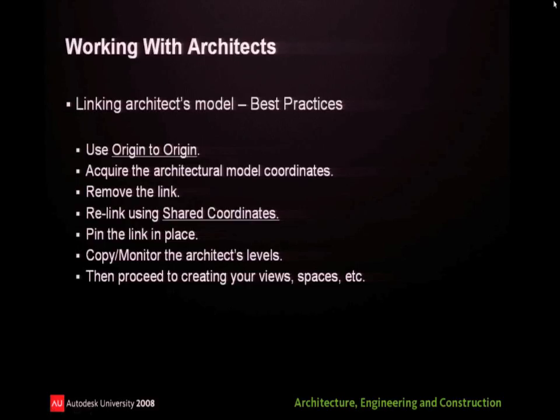But if you're electrical and you're linking my model in from central, and you have the ability to write to the architectural folder and the electrical folder, you went and selected an object through the tab process and hid an object, okay? You would then actually go into my file and check out that work set with your username, even though you've never accessed my file. And that work set would be locked with your username. You save to central, you would check everything back in, and we have to go back and reset up the files.